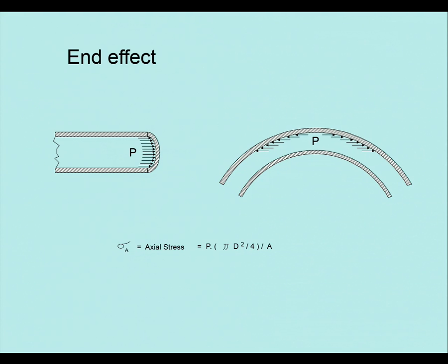If I've got a curve like that, and I've got fluid flowing around it, I've got shear stresses on the wall, and the difference in shear stress around the wall can actually give me a force in that direction from the shear. But I've not included that in here, other than to tell you it does occur.